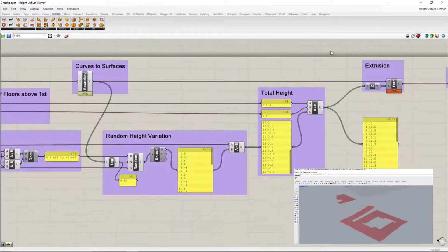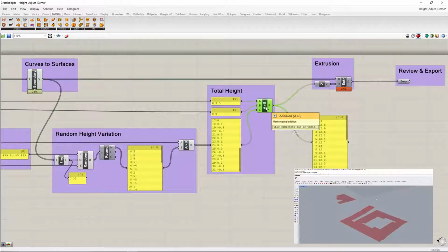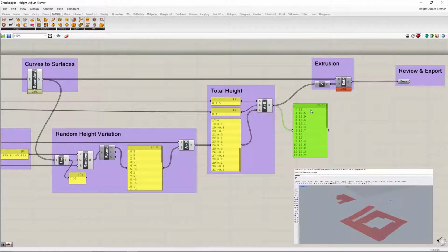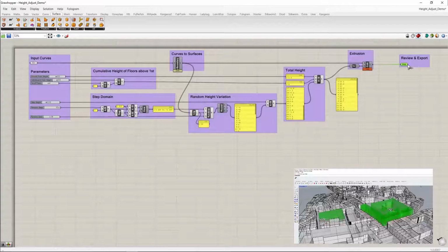The penultimate step is the extrusion of each building's base surface with the Extrude block. The required input is of course the list of base surfaces previously created and a corresponding vector. The vector contains a numeric value as well as a direction. In our case, using the Unit Z block, we convert the list of generated heights into the required vectors, in essence explaining to Grasshopper that we want to extrude upwards from the original curve in the predefined height. The final block, Brep, includes the extruded buildings.